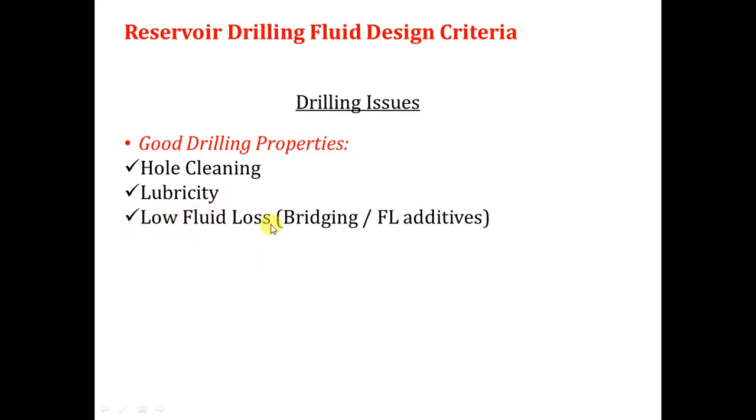The low fluid loss, especially the bridging and the fluid loss additives to be added in the reservoir zones. Actually, the low fluid loss here is very important because, as I told you, the filtrate may make a flush to the near wellbore zone, and it leads to high skin factor or positive skin factor, and it is a very big problem. The bridging, so that we use here some materials. These materials must be non-damaging.